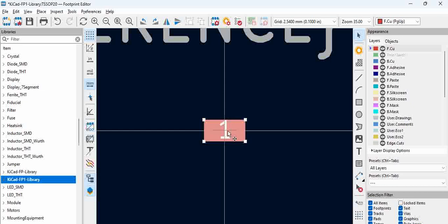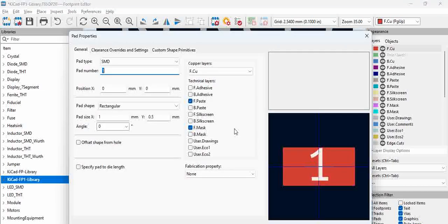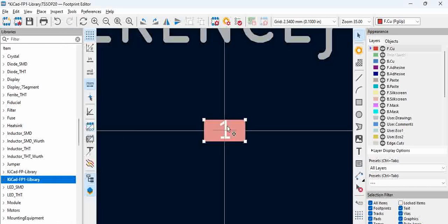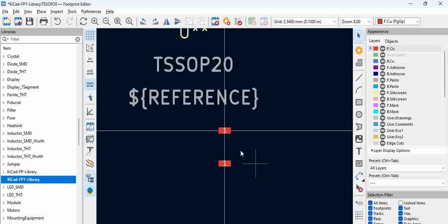Now just click on this. So now we should have 10 pads, right? So one strategy here is to make it very simple. Always position the first pad at 0 0, to have clarity on the dimensions and easy verification. Okay, and then copy, Control C, Control V, and here you can copy the pad.